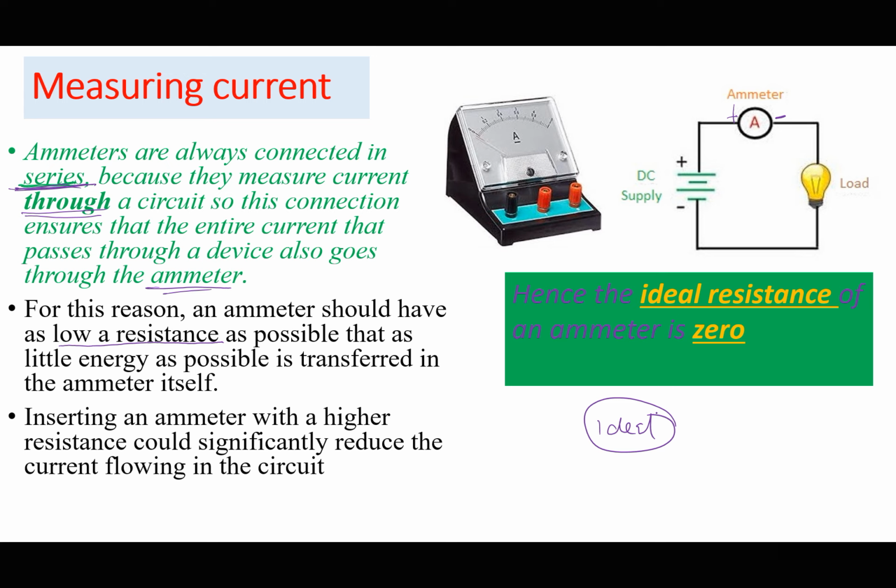However, it would be the best ammeter if its resistance were zero, but in practice we can't have such an ammeter, simply because ammeters are made up of electronic components which have some resistance, even though we try as much as possible to ensure that the resistance of the components used is extremely small. The resistance of the wires is extremely small, but still not zero.